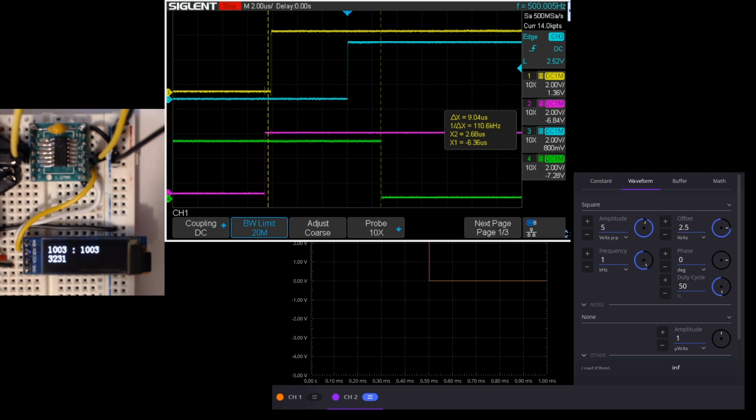So software that's part of megatinycore has to first save a bunch of context, save a bunch of state, and then it has to look at a register to see which port interrupts have actually been asserted. And then after it sees that, one at a time, it can run the interrupt service routines. So there's a bunch of extra context saving that has to happen before the first interrupt service routine can start running, probably around here. And then it completes it, and then it can run the second interrupt service routine.